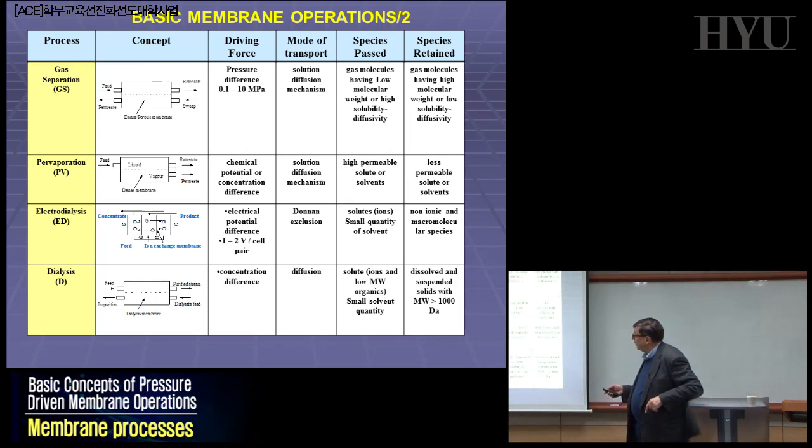But when you are talking about gas separation, pervaporation, or reverse osmosis, the chemistry of the system controls the overall process. Because in this system, as you remember, we have the solubility-diffusivity mechanism. So here there's a lot of chemistry. The solubility of one component in the polymeric phase is point number one to check.